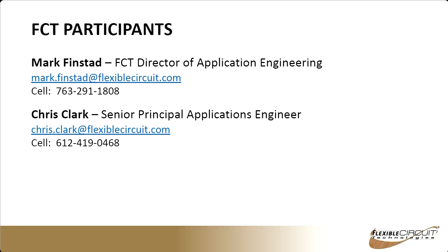Here's another one. Why use a profiled heater design? Typically speaking, the middle of your heater is going to get warmer. You can profile it such that you have a little higher watt density around the perimeter and kind of even out the whole heating area. So that would be one reason why somebody would want to use a profiled heater.